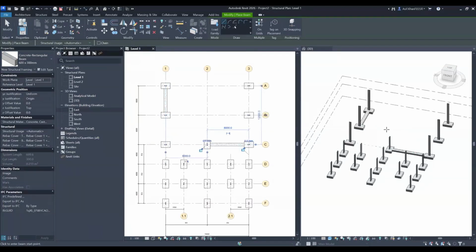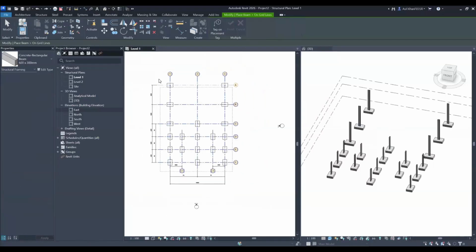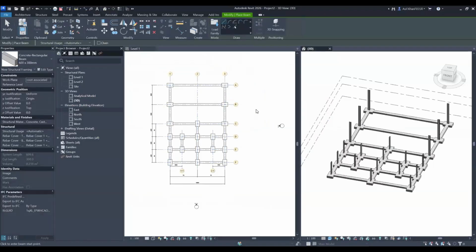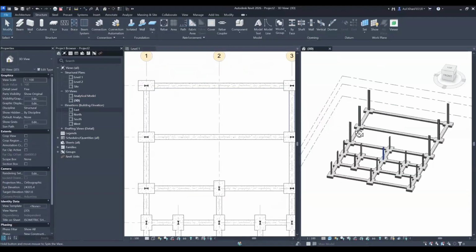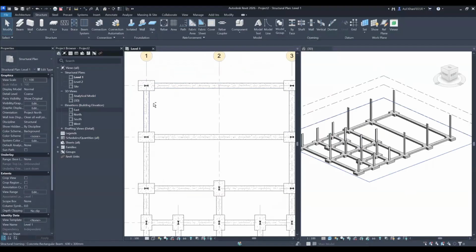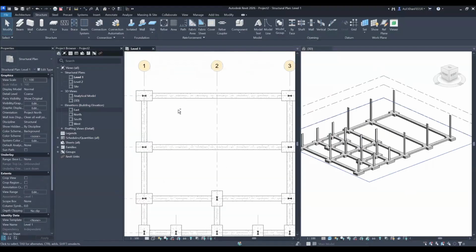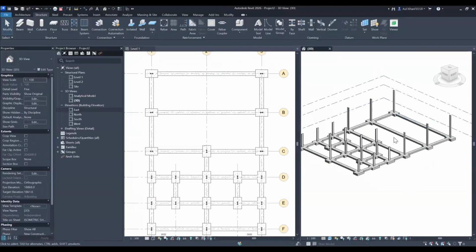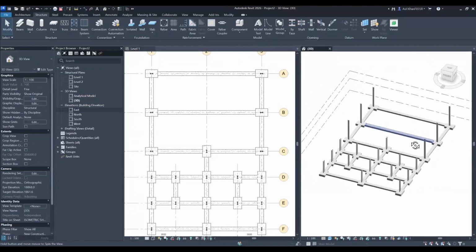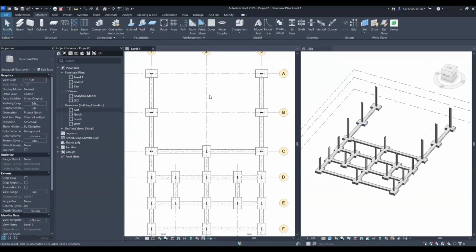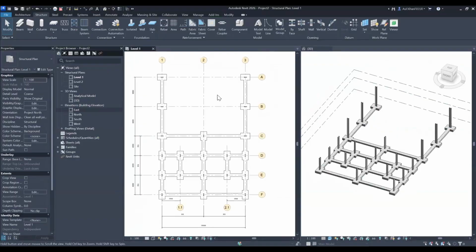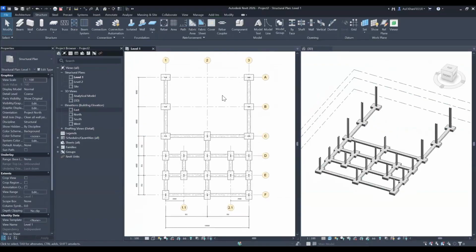As you can see, it's also drawing in 3D, but if I'm a bit lazy, what I'm going to do is select all the grid lines and press finish. My beams are done. I haven't done any line work yet. Everything is model based and easily followed, and sizes and shapes are exactly the same as I set up. Now, for example, in this project, I don't want these columns. I can just select those and delete them. There it is, done. My layout is ready, and I can put it on my sheet and go forward from there.